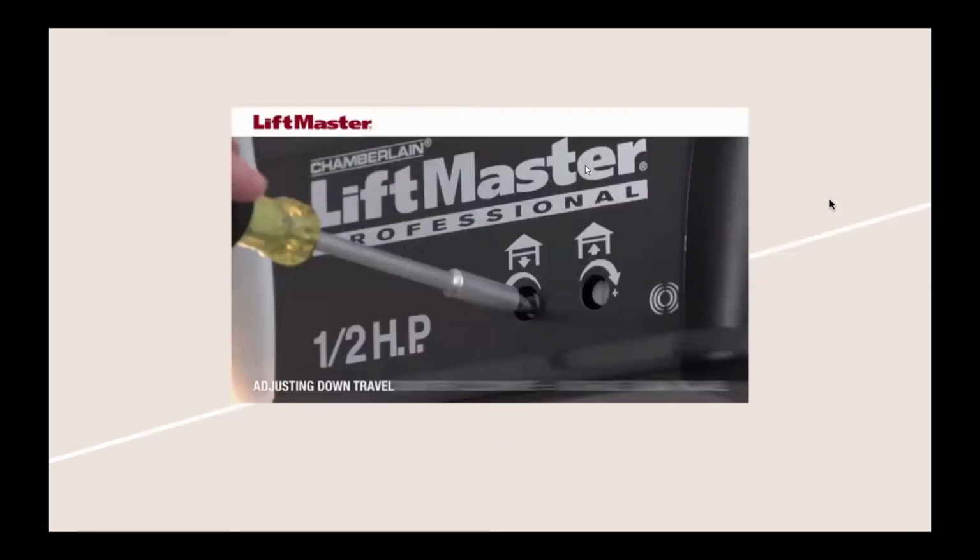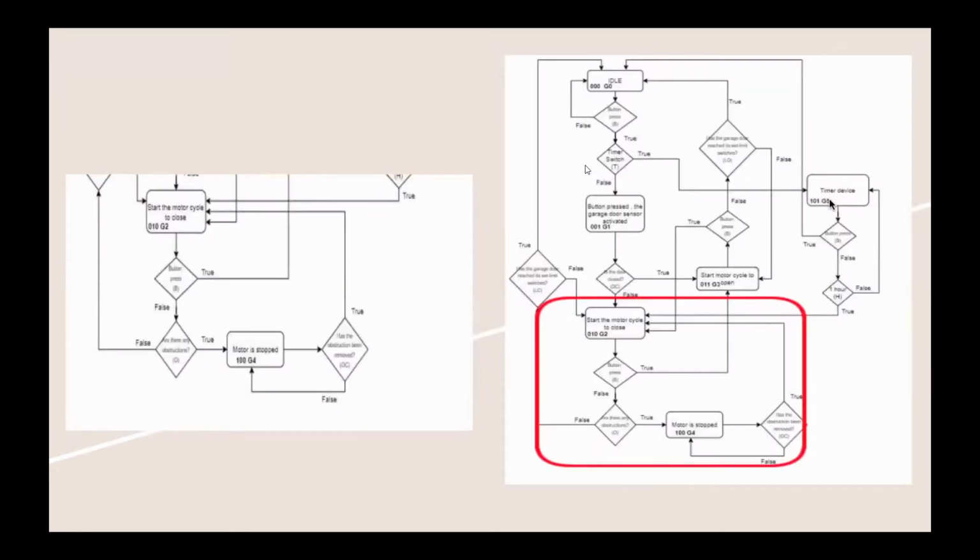Okay, so for our next state, our state 2. Let's say our garage door was open. Instead of it being closed, which would be false, we would go to our state 2, which is G2010, and that is start the motor cycle to close. So we're starting our cycle to close. And again, we have the same option as when it is opening, which is whether or not our button has been pressed.